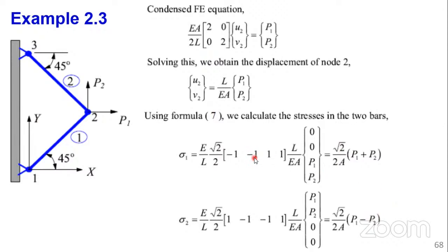So what was so important in this lecture today was about how we transform. First is derivation of the transformation matrix, so that we can now work with quantities in the global coordinate system. It should click at the back of your mind that we cannot assemble stiffness matrices for different elements which are oriented in different coordinate systems. We have to bring them to the same coordinate system.